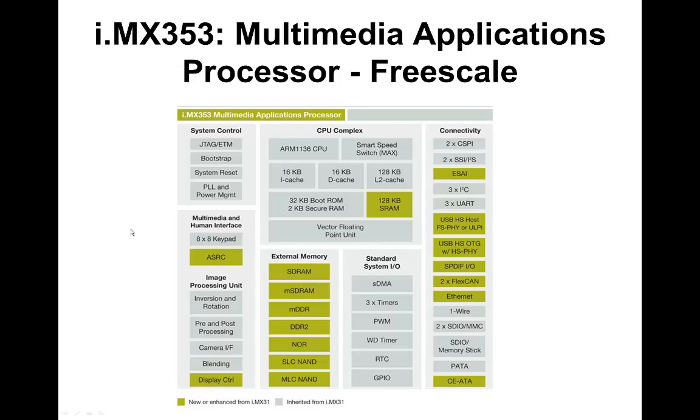So Freescale makes this applications processor here. It's got a vector processor on here, so it's kind of like VLIW, it's got an ARM core on here, another about gigahertz ARM core. It's got cache memory here. Cache memory is basically a copy of recently used instructions and/or data, and caches are usually small but fast. If you have to go access a large memory, which is slow all the time, then you can't get the processor to go very fast. So hopefully most of the time you're executing out of cache, right? If you're a CPE student, you study this at length. But basically that's what cache is. It's a recently used memory of data in an instruction memory queue.